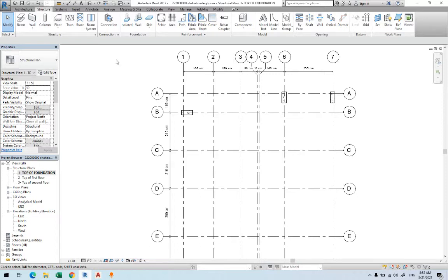So in Revit, we have different groupings. Within the structural tab, we have a grouping for foundation. There is isolated, there is wall, there is slab. Now, what does this slab mean? Sometimes you don't have a foundation, there's a slab foundation, we call it. There is just a slab, like a pavement, a concrete road. It's kind of similar to a foundation.